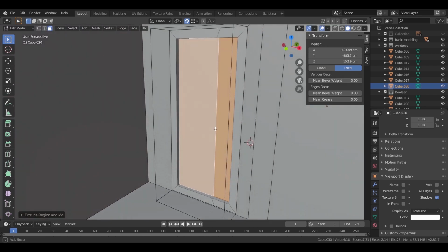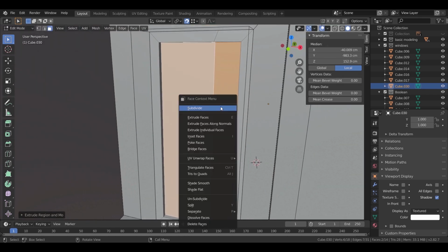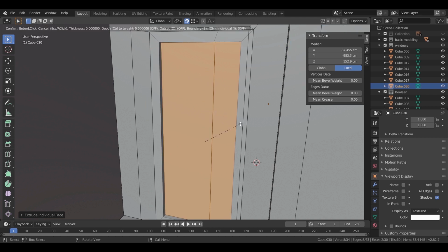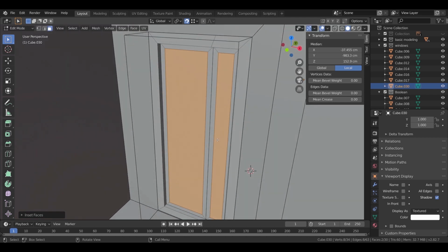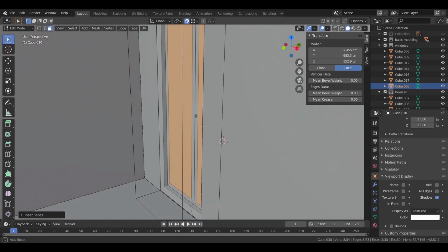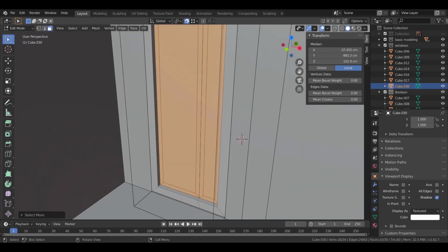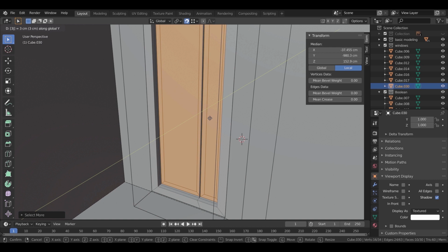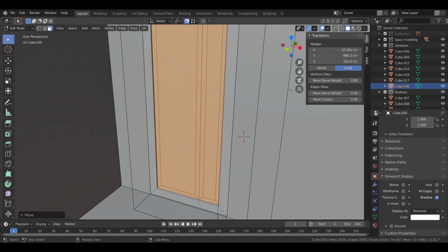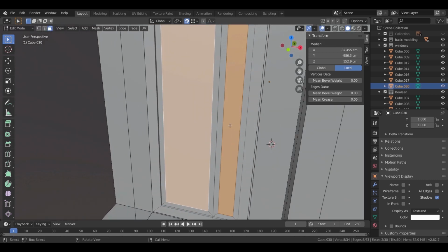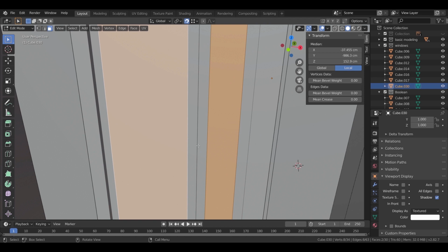Extrude to inside by 5. And inset each face by 5. First extrusion seemed big so I moved selected faces to outside by 3 as shown, and finally another inset and extrude by 2.